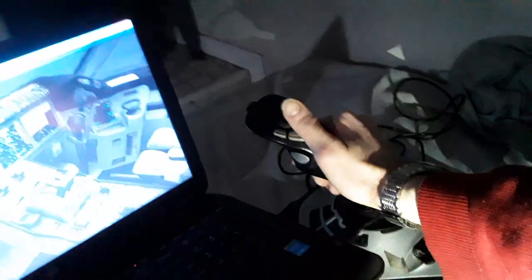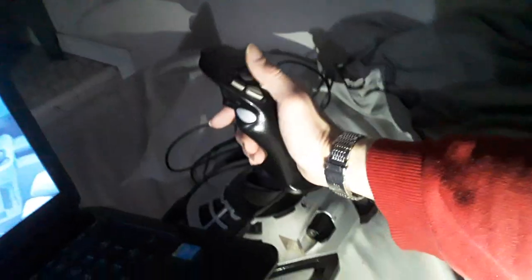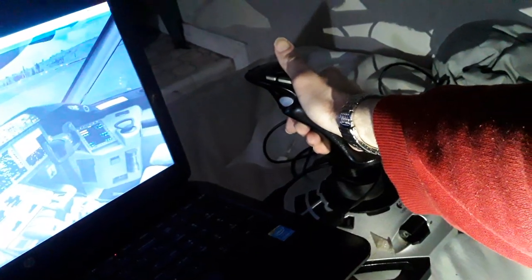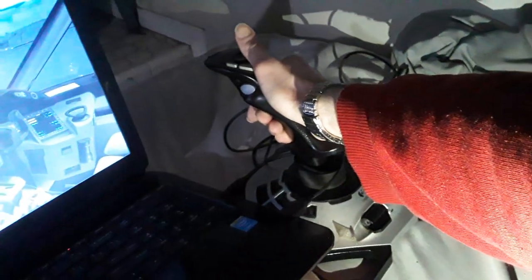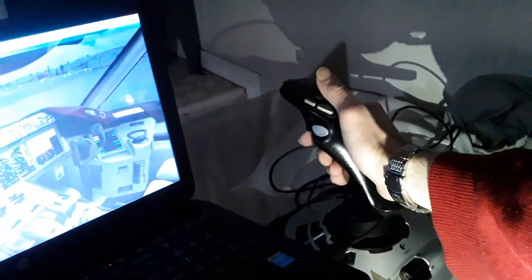Also when we release the side stick from full deflection, it comes back at 33 degrees. Also we can climb 30 degrees or 1.5 G, descend minus half G or minus 15 degrees. So we have also the alpha. When we fly level, it's 1 G actuated.